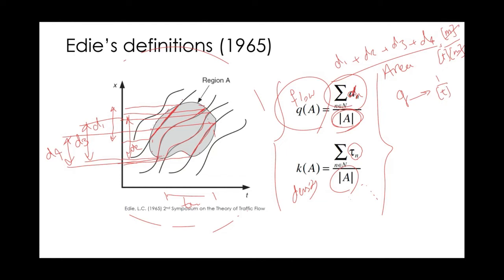Because flow is vehicles per time. So the unit is flow, I mean, past vehicles or pedestrians, doesn't matter. It doesn't have the denominator, it could be pedestrians or vehicles, right? It's 1 over a unit of time. So the unit is correct, so we can make sure this calculation is also correct. But let's have a look at density.